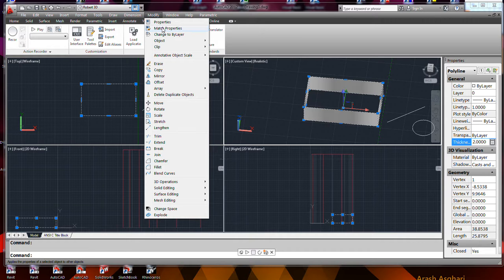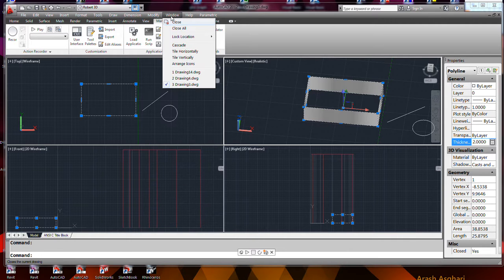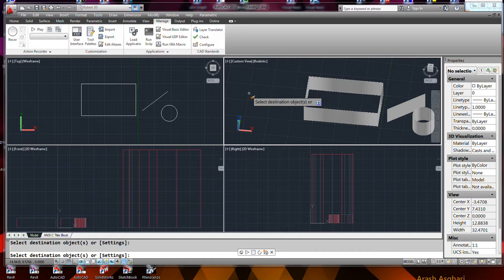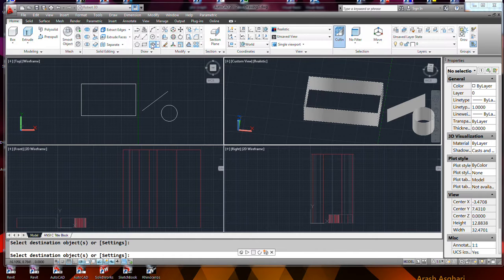If you choose match properties, and I was going to say that's something you might want to put up there, you can actually apply that to other line primitives. What's cool about this is it's pretty much a standard set of 2D drafting tools, a standard set of modifiers, and of course you can bring this up. So it's very similar to what's in the drawing menu. You've got a good subset of the 2D commands here. So that's interesting.